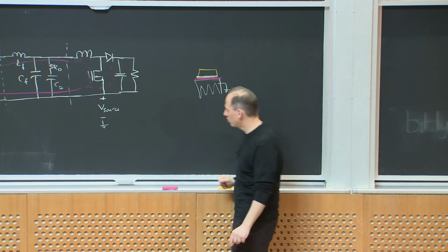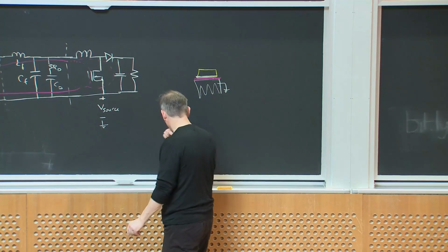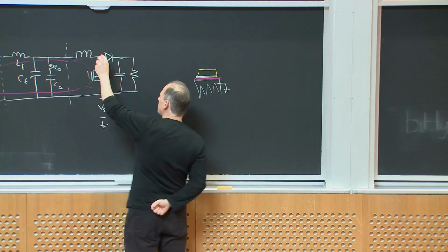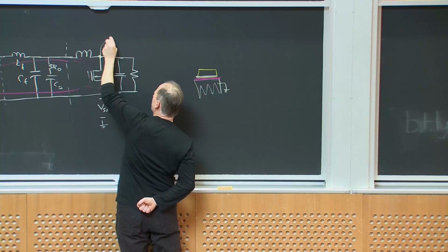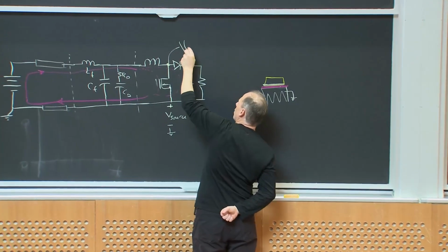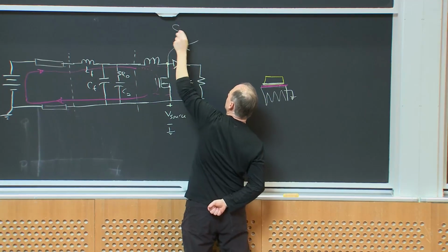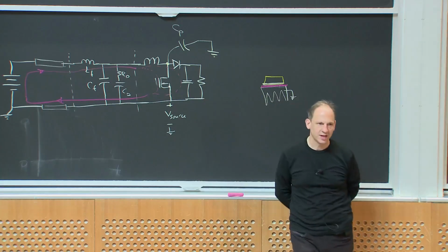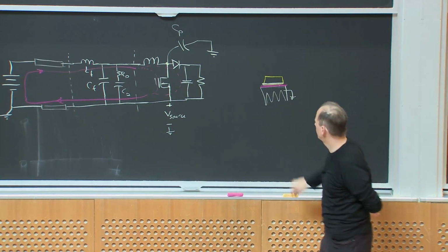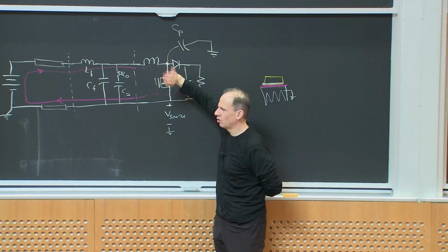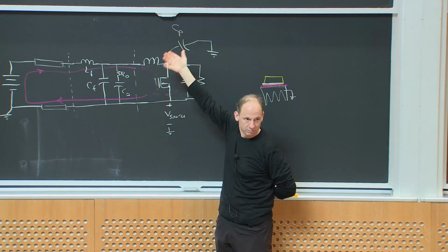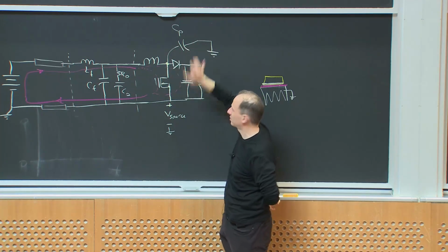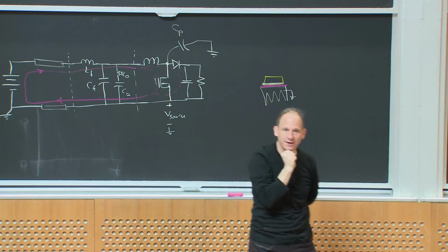So it turns out that in most power supplies like this, there's going to be a significant parasitic capacitance, I'll just call it CP, that gets back to ground, because ground is the chassis of the vehicle. Even if you didn't have a heat sink, you have a node flapping up and down, there's stuff around it, and so there is going to be some capacitance back to ground. Everybody buy that?